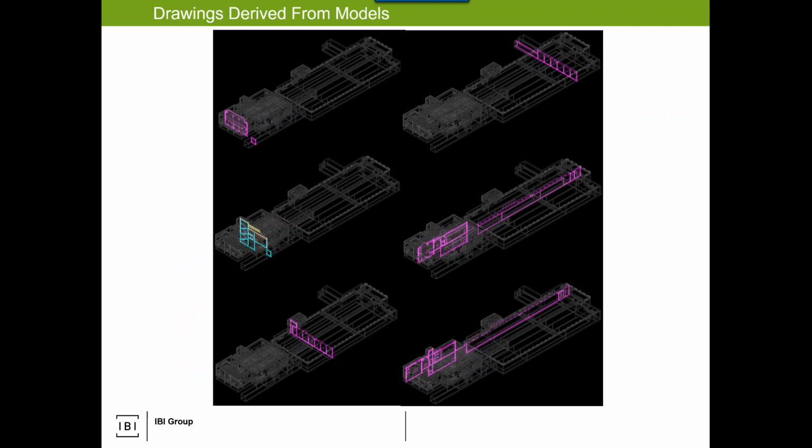So conceptually, you slice our models up. In order to achieve this, there has to be some fundamental nature for the models to be able to talk to each other. This is where the technical solution sometimes can be a burden. This example here is in the Bentley world. I just link a bunch of models together, I cut, and everything works quite nicely. In the Revit world, when you link a bunch of models together, those linked entities act as blobs.